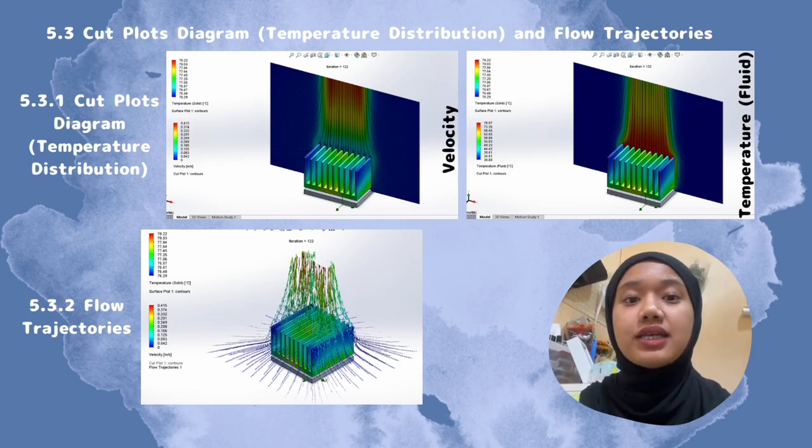The airflow path suggests that fin spacing permits adequate air movement for effective passive heat removal. The temperature cut plot indicates that warmer air is located near the heat sink surfaces, while cooler air is found further away. This distribution demonstrates effective heat transfer from solid surfaces to surrounding air with a gradual temperature decay that reflects strong thermal interaction during steady-state operation.